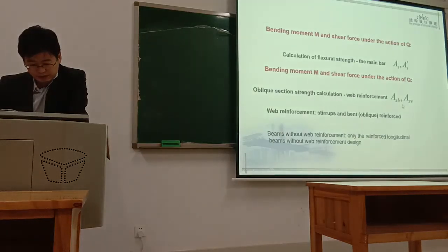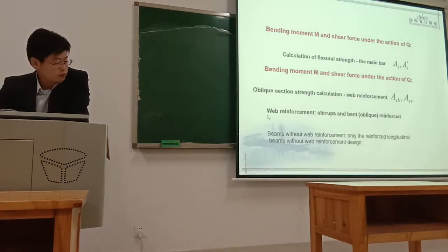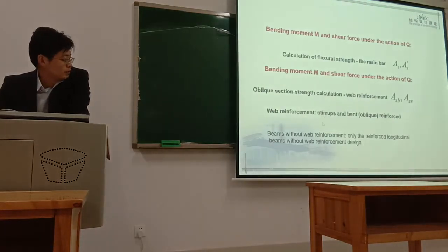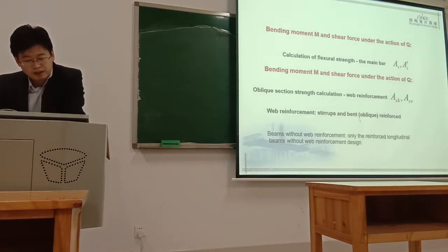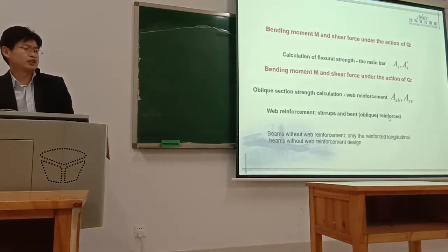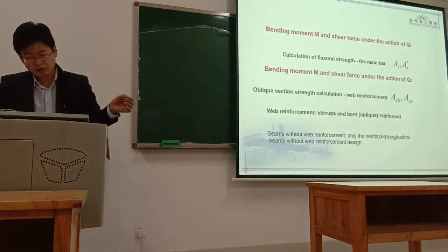Shear force. So what is the web reinforcement? Actually, web reinforcement mainly includes the stirrup, the bent-up bar, or link reinforcement. Actually, bent-up reinforcement is part of the longitudinal reinforcement. Just at that point, it bends up.